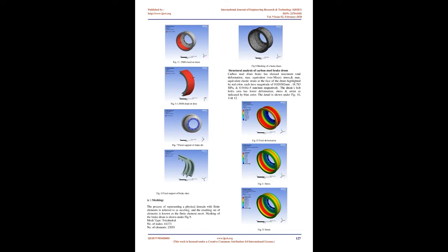8. The determination of brake temperature is important for the analysis and design of a brake system. Excessive temperatures will cause a decrease in brake torque production, commonly called brake fade, and may cause increased brake lining wear, brake system failure, and damage to adjacent components such as bearings and tires.